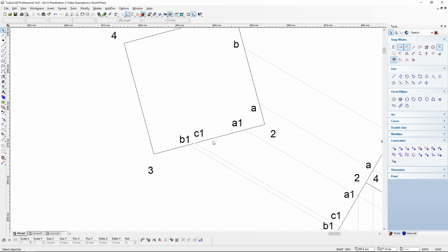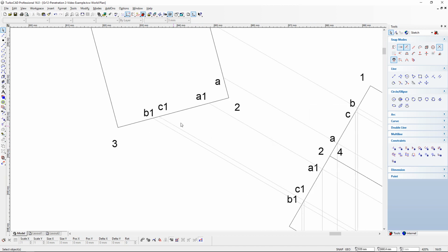It's very important to keep your labels close to your projections, because obviously on paper you will see these lines appearing much closer to one another. And if you do not label them, you will definitely get confused with which line or projection will be which. So please always label as you draw.